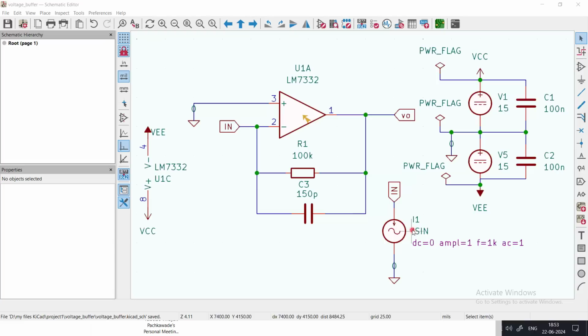So remember, now the input is the current to the circuit, output is the voltage. So obviously the transfer function of this circuit is voltage divided by the current, that is output divided by input, and voltage divided by current is resistance R. So this resistance R is going to set the gain of this amplifier, and it is also called a current to voltage converter or trans resistance amplifier. Since capacitance is also included, this is called a trans impedance amplifier.